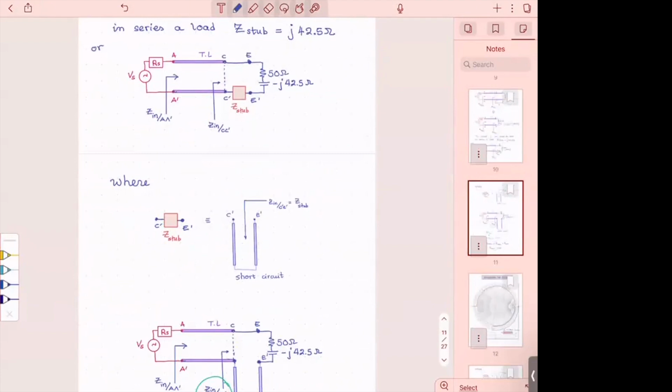So I identified exactly what I said. All of this is like a schematic representation of all of the discussion we had, right? So we identify that we can put a short-circuited stub that at this point is going to create an inductance which is going to cancel that. All right, and that is somewhere in the line. Remember we are at E prime.